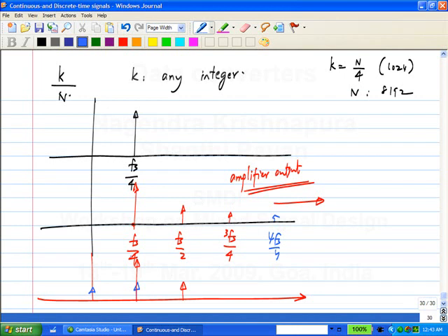You are taking an N-point DFT, an 8192 point DFT, but it's useless. Everything is 0 except these points. Whereas with 8192 points, you will be able to get 4097 different points. So ideally, you should be able to get this much. So what was wrong here? You have chosen it such that the harmonics fall on top of the original. Ideally, if you take an N-point DFT, we should be able to distinguish N by 2 different components. So what should you do here?